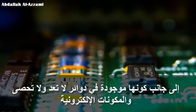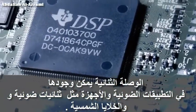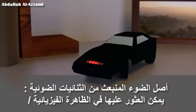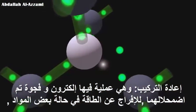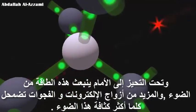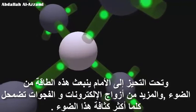Besides being present in countless circuits and electronic components, PN junctions can also be found in optoelectronic applications, in devices such as LEDs, photodiodes, and solar cells. The origin of the light emitted from an LED can be found in the physical phenomenon of recombination. Recombination is a process where an electron and a hole are annihilated, releasing energy. In the case of certain materials, and under forward bias, this energy is emitted as light. The more electron-hole pairs recombine, the more intense this light is.